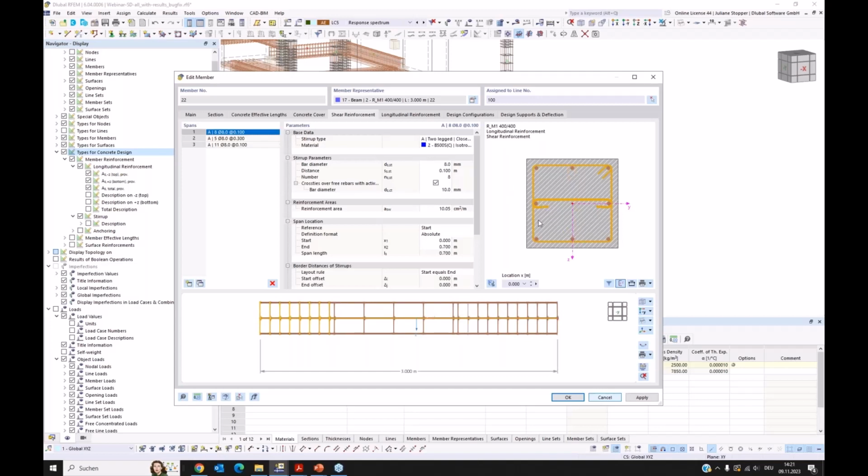and you can modify it via clicking on the longitudinal bars. So if you have more longitudinal bars and you don't want cross ties between all of them, you can just click on the longitudinal bar and the cross tie will disappear or come back. Yeah, this is the thing about the cross ties.